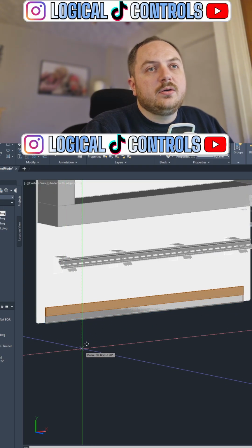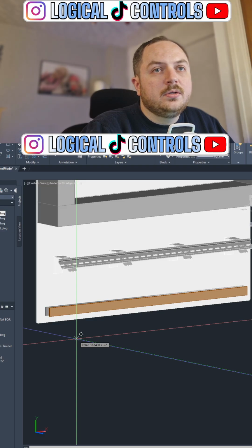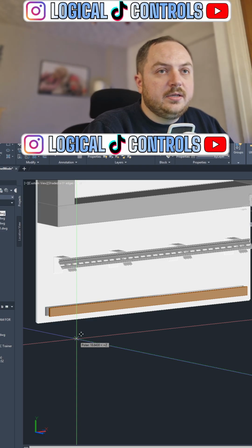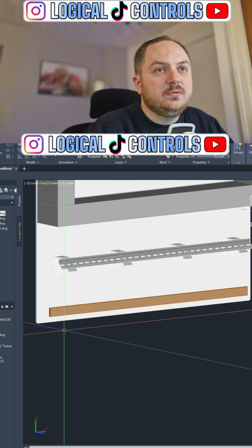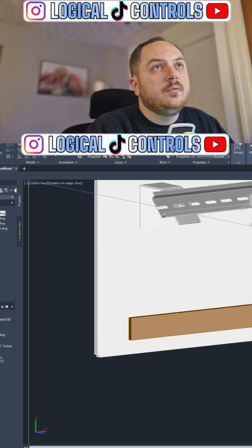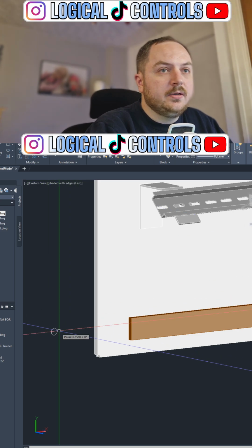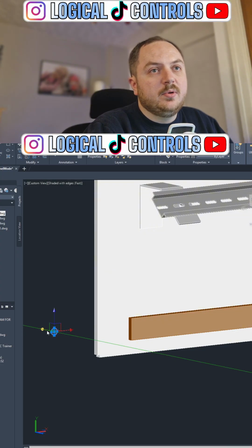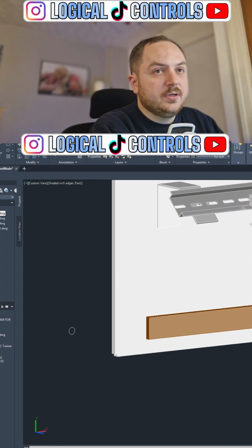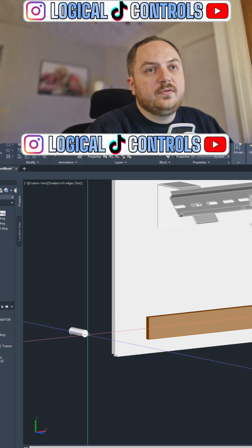Okay, let's bring that up a little bit. It doesn't really have to be critical where this goes. Let's bring it out by 20mm. And let's just make a couple of bolts to go through. Let's do M8, an 8mm bolt. Press pull. Make that 25 or something.